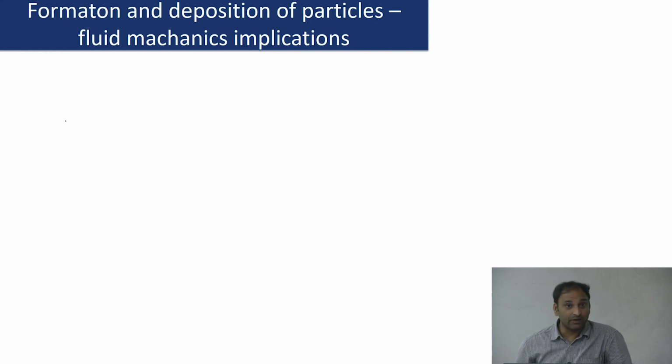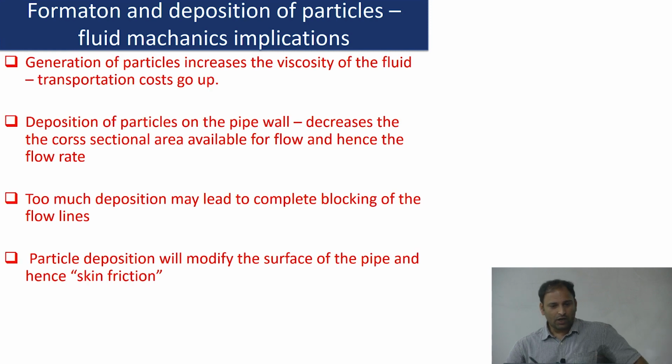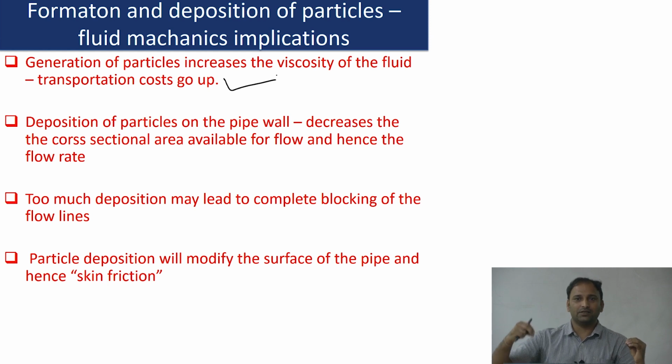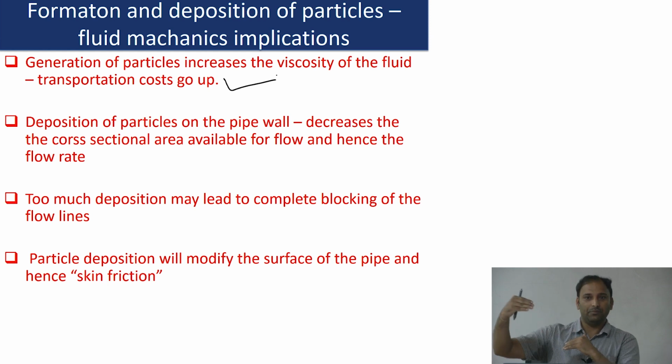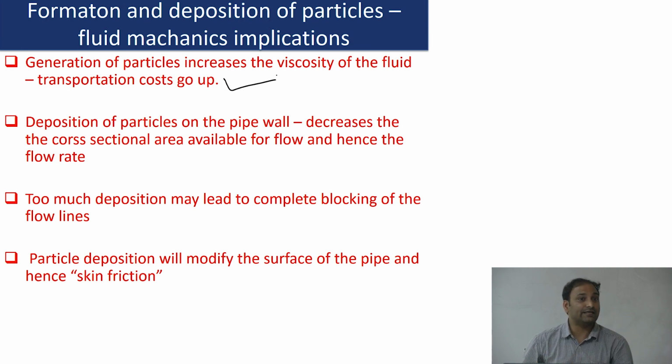Okay, so of course there are several implications, right? Now we know that whenever there is a generation of particles, the viscosity of the fluid goes up, right? We saw an example in one of the previous lectures, wherein you have a base fluid and you start adding particles. We said that the viscosity was going up, right? Therefore the generation of particles can lead to a significant increase in the viscosity of the fluid. Therefore there are going to be associated transportation costs, so one has to worry about that.